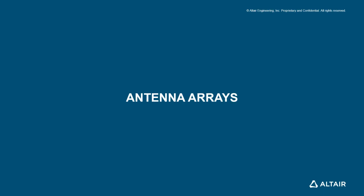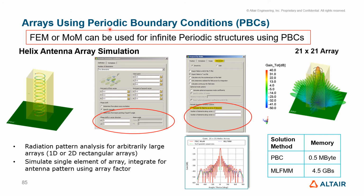So far, we talked about individual antenna elements and how we can handle them with the different numerical methodologies and simulation methods that we have. Let's briefly take a look at antenna arrays. How do we analyze antenna arrays using modeling and simulation? One way to do that is using periodic boundary conditions. Essentially, if you have a single element, you can put boundaries around it, which essentially analytically duplicate this element to infinity in both directions. So you have an infinite array of these, let's say the helix antenna we are showing here.